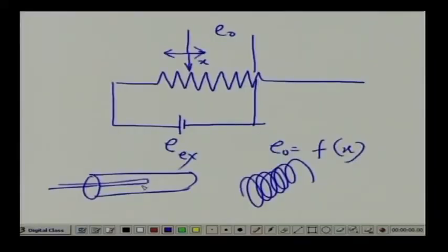In this case there is no question of how fine and how close the windings on the outside are; that does not matter, because the resolution here depends on the magnetic linkage between the two. It does not depend on the physical position or the physical number of coils which get in touch with the wiper. So, that is a great advantage of the LVDT.